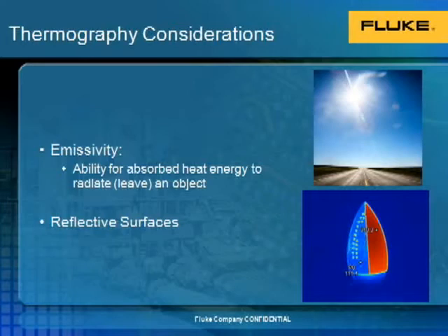As you see in the picture of the iron, the right side of the iron that is red is coated in a black paint, which makes it much more friendly to a thermal imager to get an accurate temperature reading. The left side, the blue side, is not coated and is very shiny and reflective, which leads to false readings. Be aware that even when you're dealing with reflective surfaces, there are certain ways that you can remedy those to get better and more accurate readings.